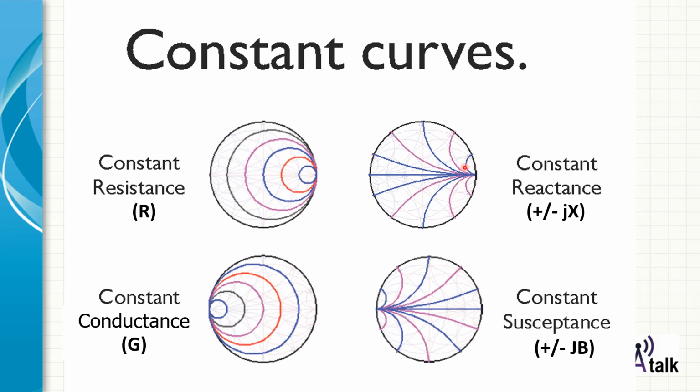The horn-shaped curves on a Smith chart are reactance, those horns coming from the right side, and this is constant reactance of maybe 50 jX, this might be 100 jX, a positive jX, and negative jX down here, okay? And these are curves or horns of constant susceptance, which is the inverse of reactance. All right, and so there's a constant positive susceptance curve and a negative susceptance curve. You'll see how this maps out in the Smith chart in a moment.